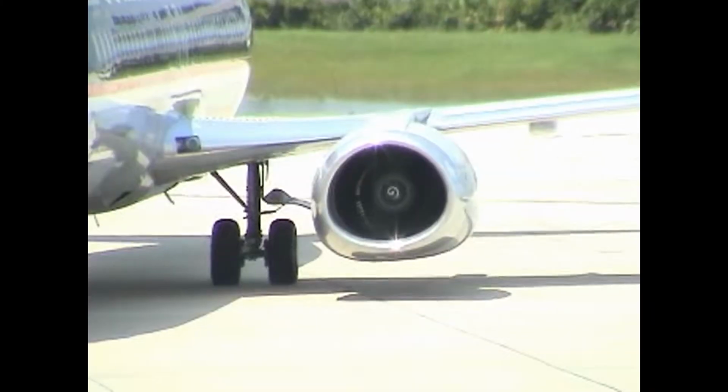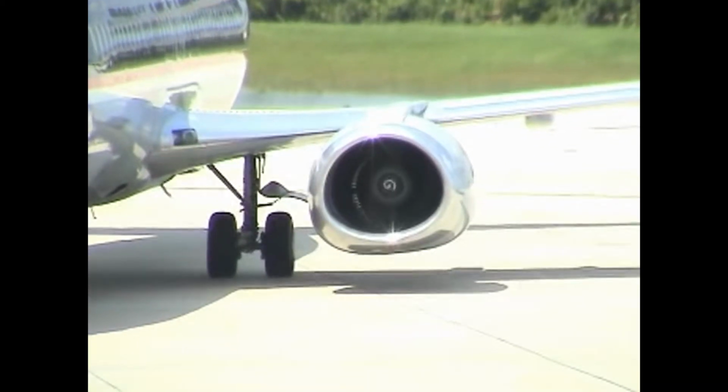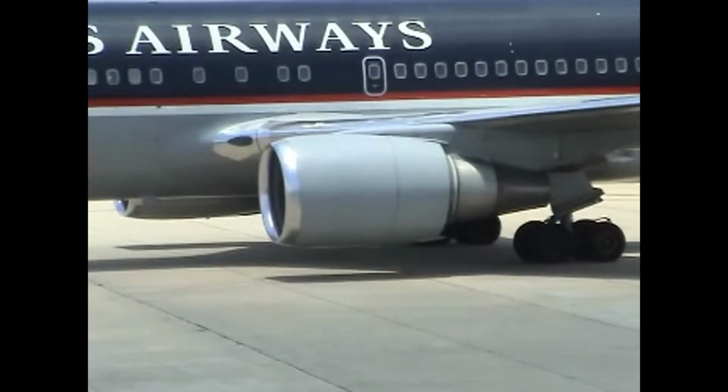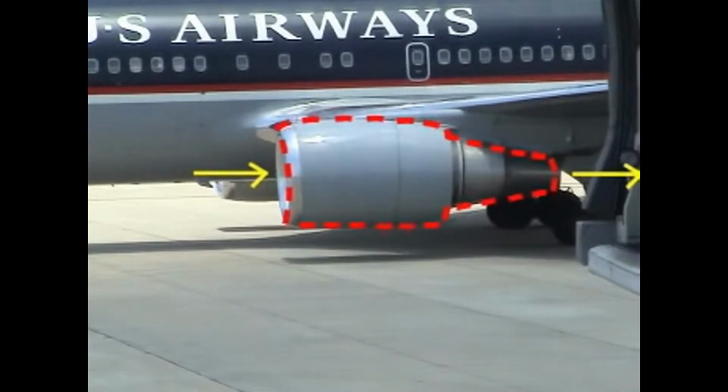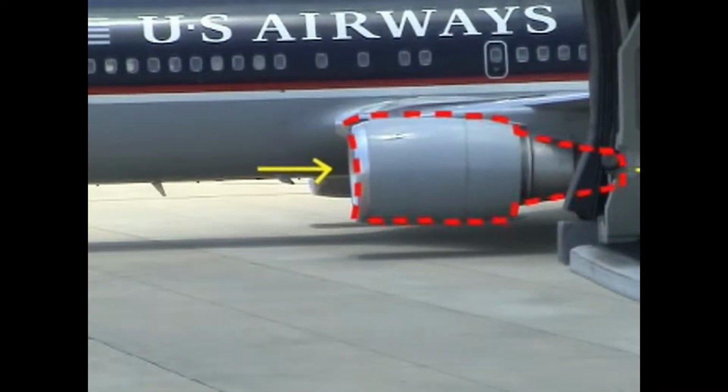This reference frame is inferior to the Eulerian approach, however, in treating the airflow through a jet engine. In this case, a control volume is fixed to the jet engine with air flowing through it. Likewise, an appropriate Eulerian control volume for this hairdryer is fixed to the dryer itself rather than to the air passing through it. In this simple example, the control volume has one inlet and one outlet, and its lateral sides are impermeable to the air. Electrical energy enters the control volume, however, in order to heat the air and drive the blower that moves it.